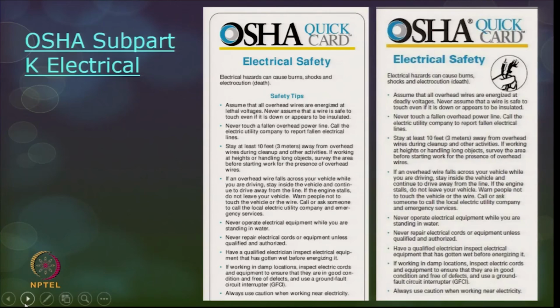Most of this material is taken from OSHA Subpart K electrical, and a quick card on electrical safety. Electrical hazards cause burns, shocks and electrocution. Some of the safety tips are also given here. Assume that all overhead electrical wires are energized. Never assume a wire is safe to touch even if it is down or appears to be insulated. Never touch a fallen overhead power line. Call the electric utility company to report all these power lines.